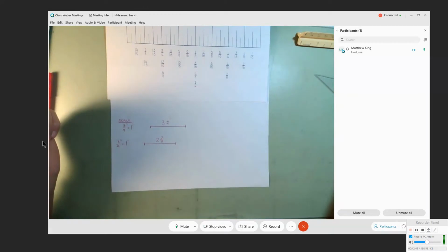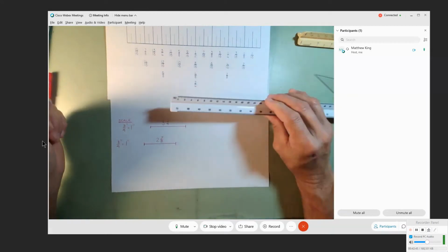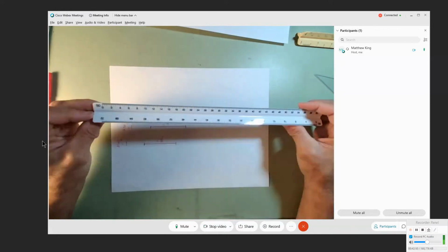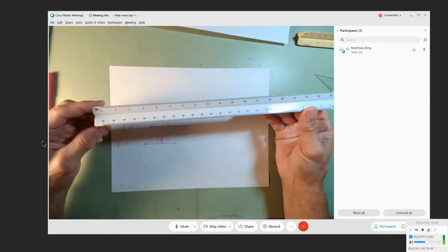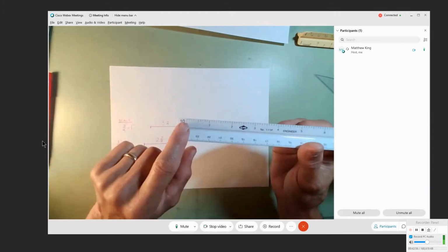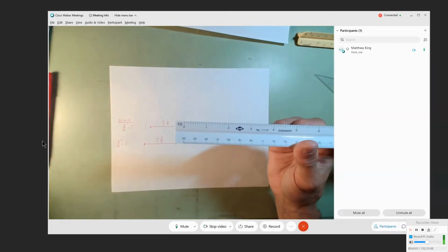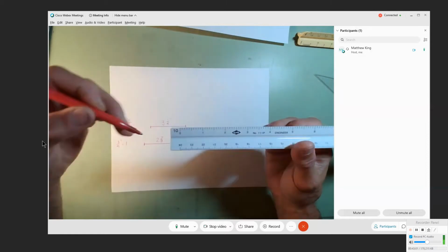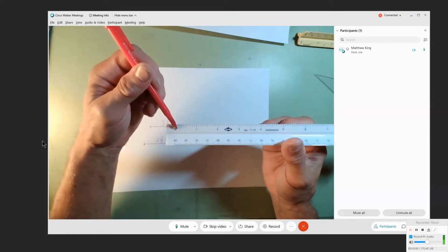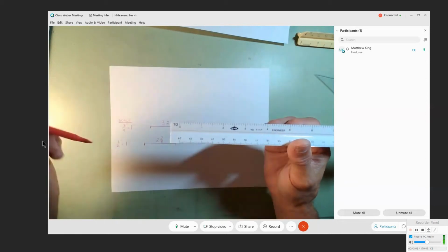All right, I'm going to show you one more thing here on the other scale, the engineering scale. Okay, find your engineering scale and locate the 10 on the outer edge, 10. Now that 10 is the equivalent of full scale or the 16ths on the other scale, whereas 0 to 1 is a full inch. So if we got an inch of rain on this scale we'd measure, that's what it would be.